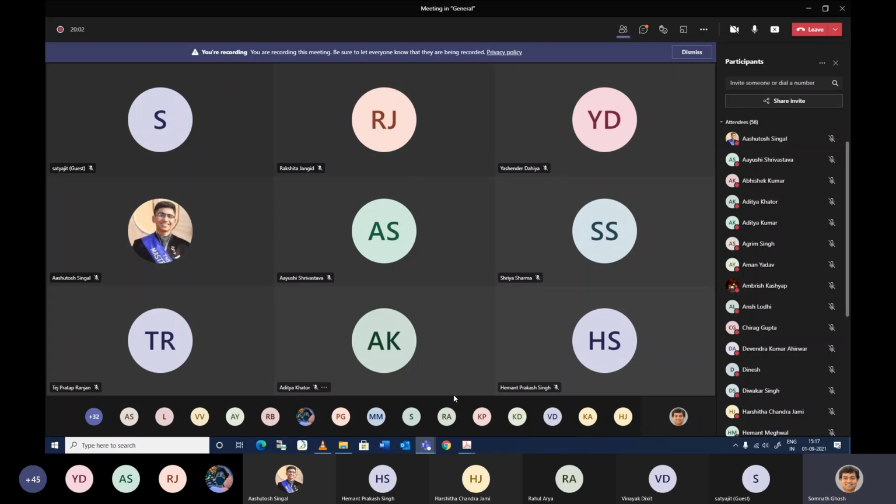No. So for Bernoulli's experiment, you need one set of data. For one flow rate, you can get the energy, and if you quantify the volumetric flow rate at different time steps, then you can get another set of energy data. Okay, for every volumetric flow rate, you get one set of energy data. Then you can compare with time if there are any changes in energy for a particular point or not. Okay, but you can write it with one set of energy data also.